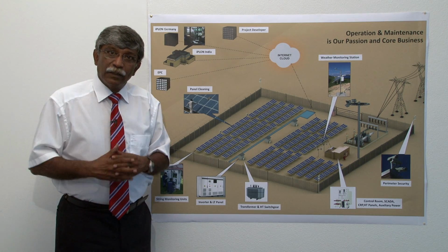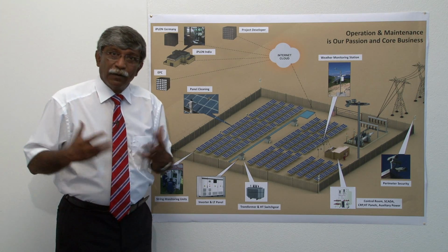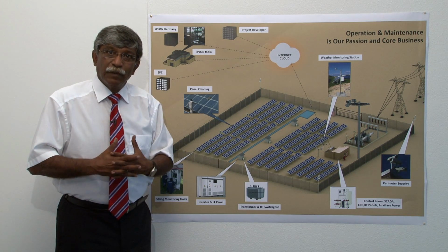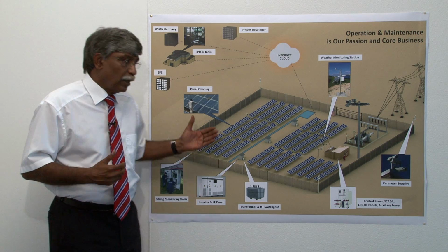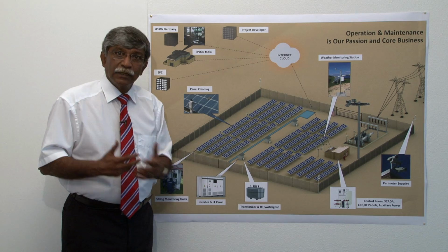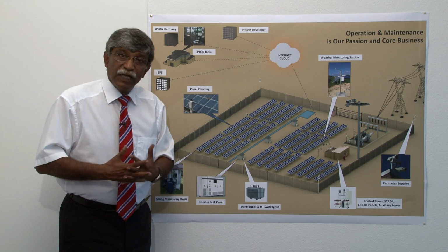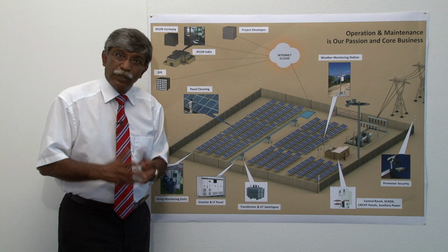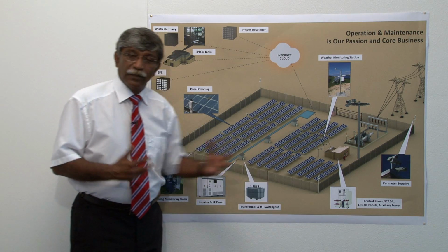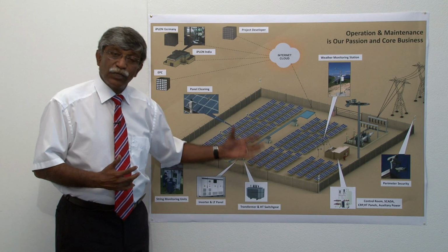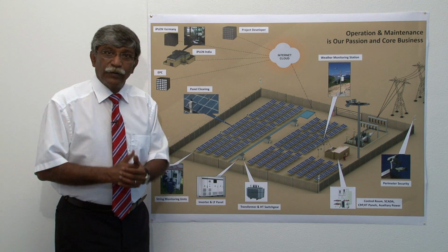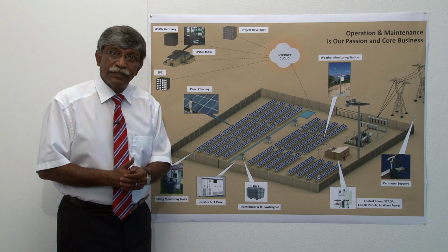And if you look at the things which go wrong, from the cost point of view, about 40% of the effort and money is needed for standard preventive maintenance. The inverter replacement and costs are between 20 to 30%. And on the AC side also, because things go wrong due to isolation and earth shorting issues, you should calculate with about 15 to 20%.